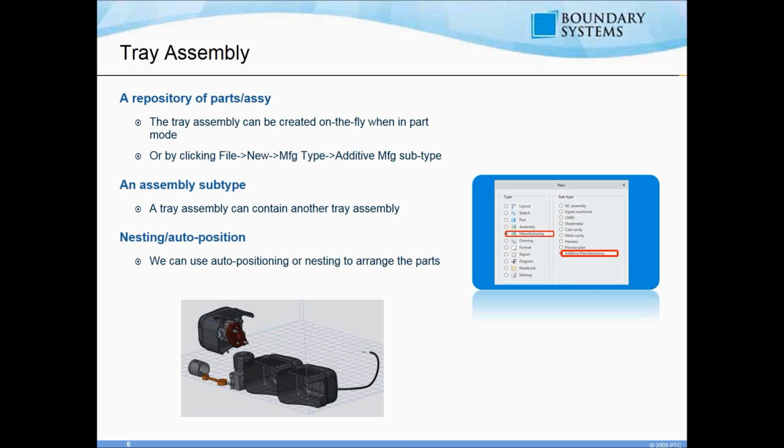In other words, the goal is to eventually be able to manipulate everything 3D print wise from inside of Creo, so that all you do is click one button and it starts manipulating your 3D printer. One of the steps to that is the tray assembly, where you can position the different components you want to build. This user interface also brings in many of the tools you need to help in the 3D print process. You can do things like printability validation. You can clip your model, reposition your model, and scale it up or down, all from the same user interface.